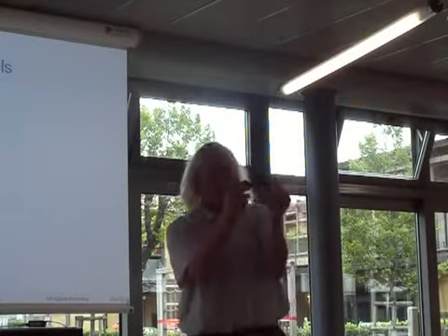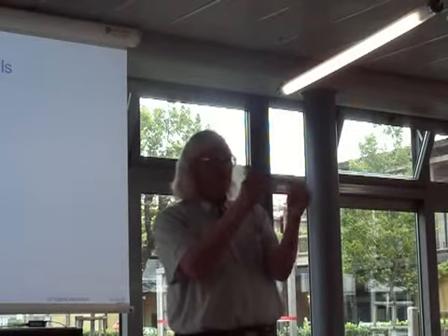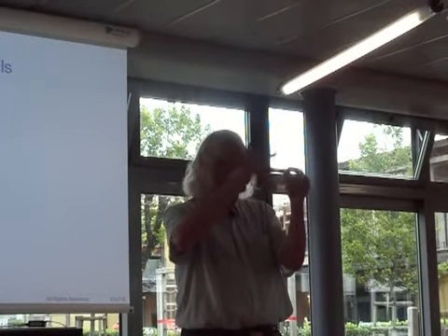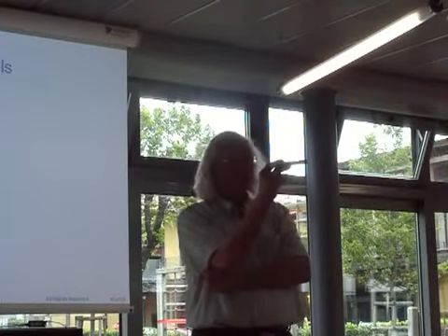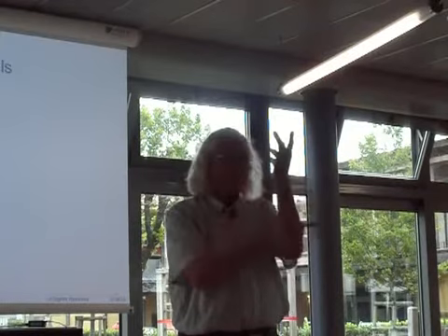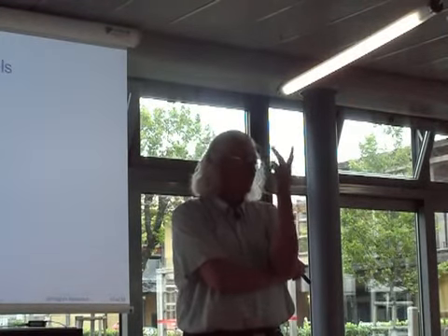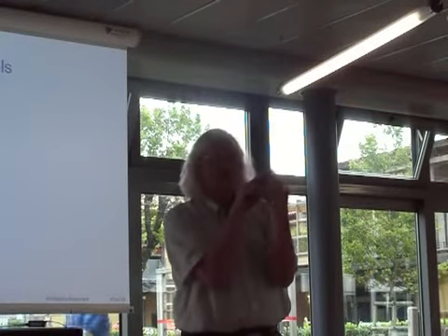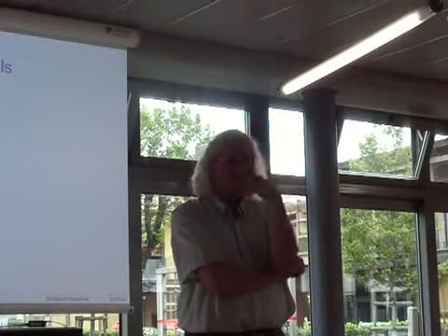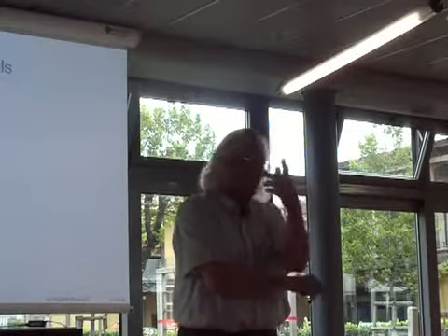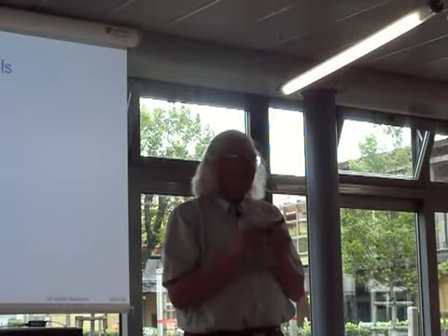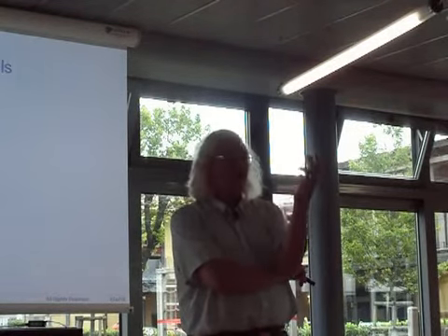Well, let's think about this a little bit. First of all, almost all of the experiments come from doing tension tests or torsion tests or some combinations of tension and torsion. If the loading situations I can deal with are tension and torsion, I have only two variables: shear stress, tension stress, and of course the ratio between those two. How many ways can you combine two variables? I can add them, I can multiply them, I can square them and take the square root. There aren't very many ways of combining these. But what you find in the literature is that people make very small changes to the fundamental models, and then they publish this as a new model.